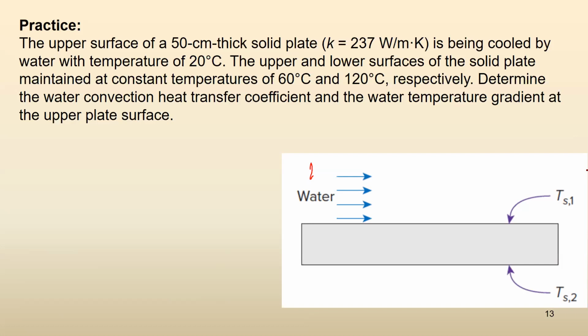So first of all, you need to read the properties. Keep in mind that you need to read the properties at the film temperature for the water, not at the water temperature or at the upper surface temperature, but at the film temperature.